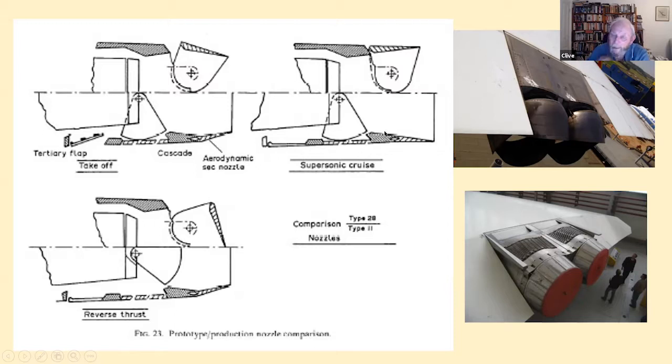Because of problems with transonic performance, where the engine doesn't normally produce enough pressure ratio to fill this nozzle, you can get some substantial installation losses in transonic conditions if you got the nozzle wrong. There was a blow-in door here which supplied extra air in transonic conditions. You can see the grill in this one, and to be honest, they're not really subsonic designs, are they? There's the blow-in doors just ahead of it there.